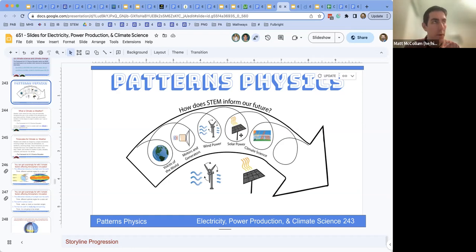I'll hand it off to you. Yeah, just a few tips when you're thinking about doing this. We have the Vernier solar cells. We connect them to the energy sensors that we also used for the wind turbines, so they're familiar with the technology. And you really do need to think about light that is scattered off of different things. It doesn't necessarily have to be a bright sunny day, though of course that is oftentimes best.